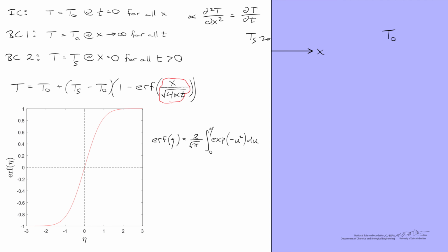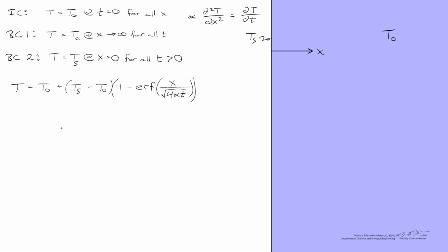And in that case, a short period of time, there isn't enough time for the heat to diffuse even through short distances. And we'll find that T is equal to T naught at short distances into the surface. At the other extreme, for x equals 0, the error function of 0 is equal to 0, and we'll find that T is equal to Ts, the surface temperature. That applies for our boundary condition at all points in time.